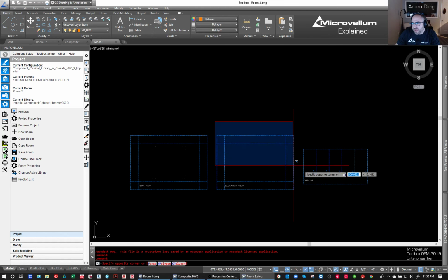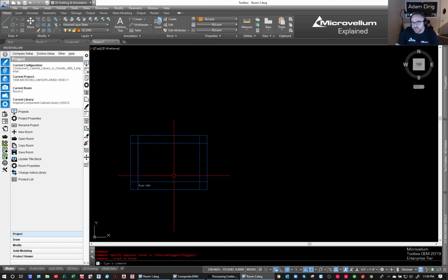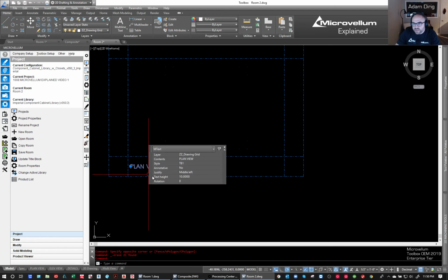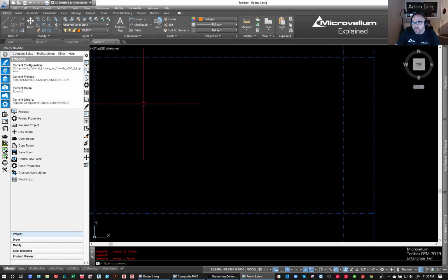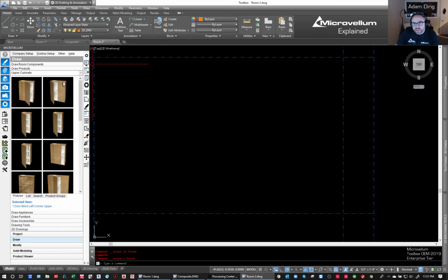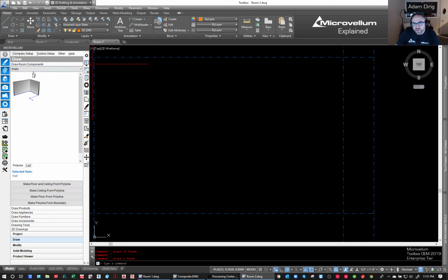Now in my other drawing, I actually deleted these. I'll do the same here. And I deleted this because I didn't like it. And now I'm going to draw a wall. So I'm going to go down to draw. I'm in products right now. I'm going to go to room components and I need to draw a wall. So I'm going to pick points to place the wall. And I'm just going to go to the 0, 0, 0 point. And I'm going to make this wall 100 inches.